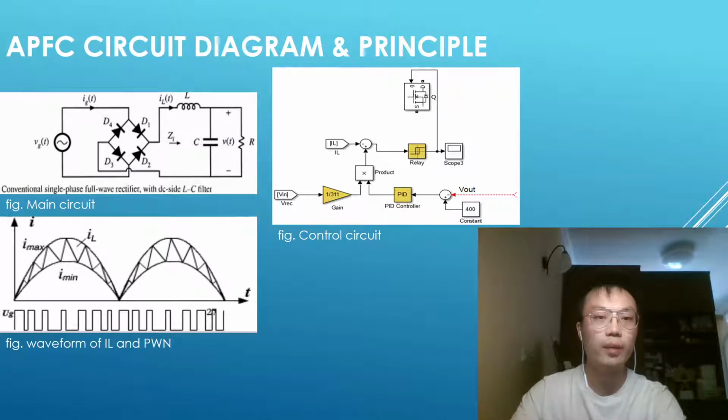In this circuit, the capacitor gets discharged when the diodes are reverse biased and no current flows through. Then, when the capacitor voltage gets lower than the grid, the diode conducts and the inductor current increases. When the inductor current exceeds the load current, the capacitor voltage starts increasing. At some point, the capacitor voltage exceeds the grid voltage again, and the diode stays on.